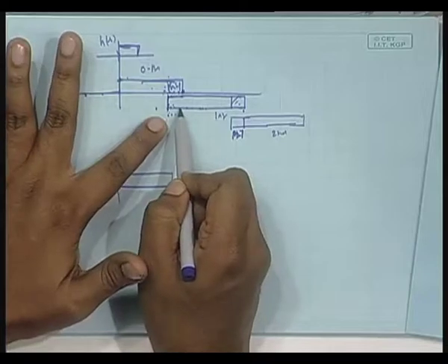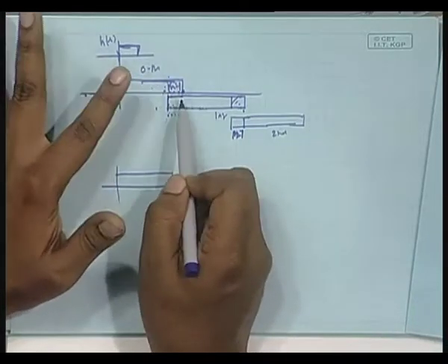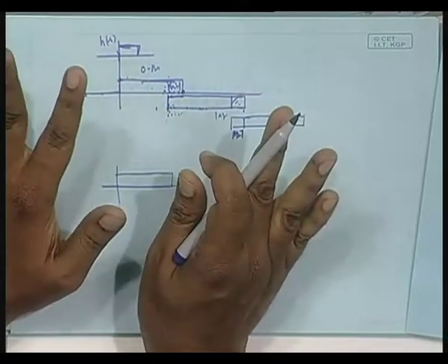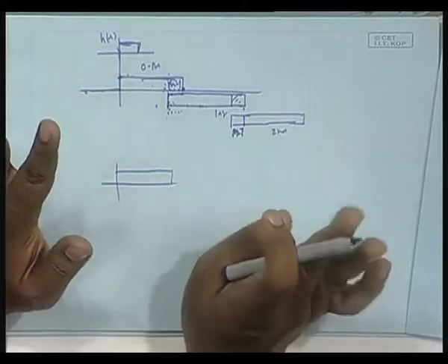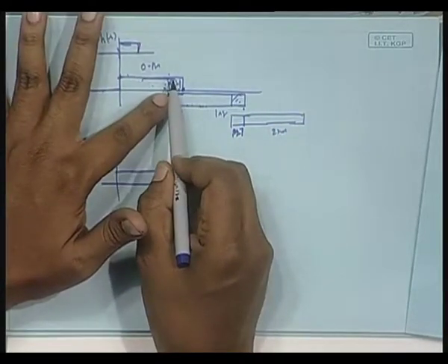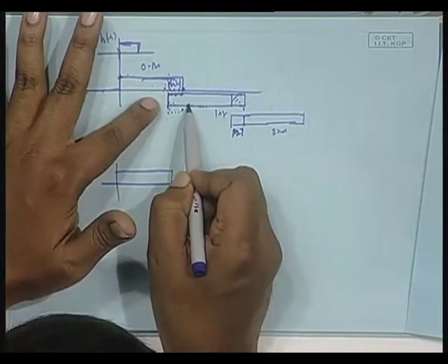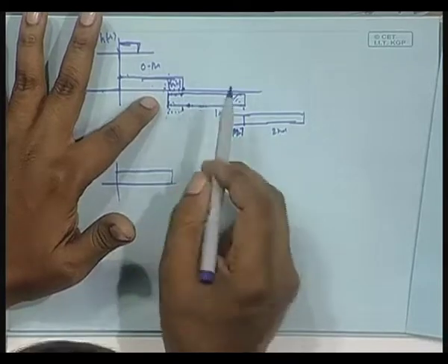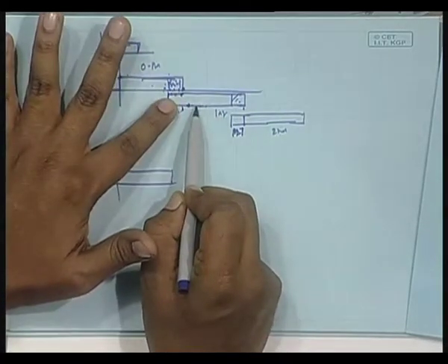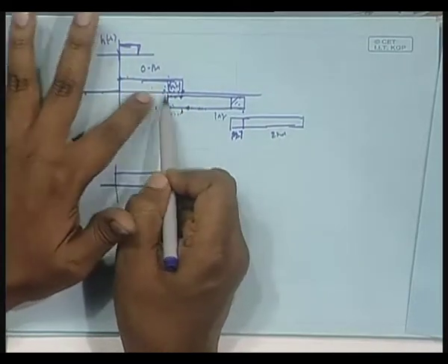Firstly, these points give me wrong result, even if weights did not change, and now weights also have changed. So, at these points I really do not want the output. Are you getting me? I will not need them because the correct desired things are already computed. I will throw them away. But from this point onwards, I need the output for this block only with the filter weight obtained for this block, and that I am doing, because for that I do not need any data from the left of this.